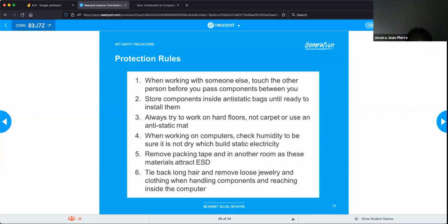Reference like a condensation, a sweat, it might cause the equipment to, because I know it gets really hot sometimes, the heat and things, and that's just my small computer, let alone when you have a whole station area of computer items. There you go, moisture. Thanks, DW. So Jessica, you were right. It creates condensation based on the humidity, and the moisture can do 2 things. It can create a grounding between 2 connections, causing a short, or it can actually cause the components to start to oxidize or rust. That's right. Which means that they will not have as good of a connection and they will not function properly.